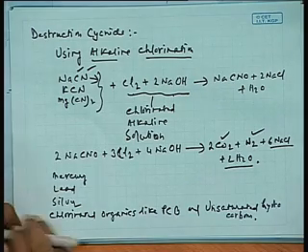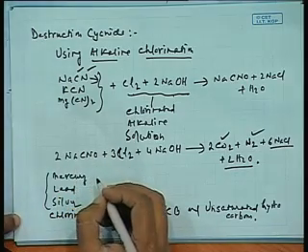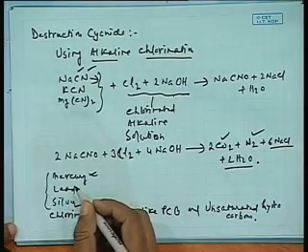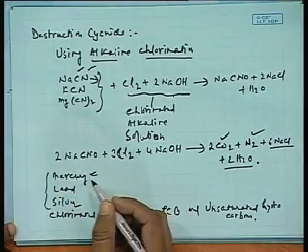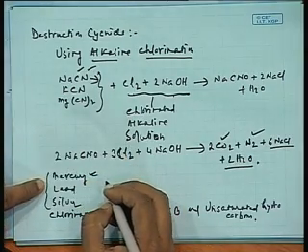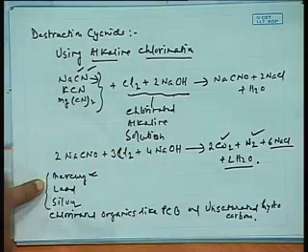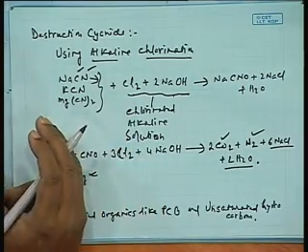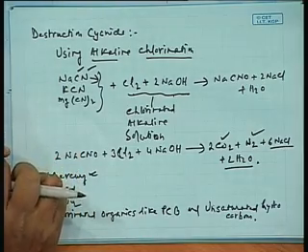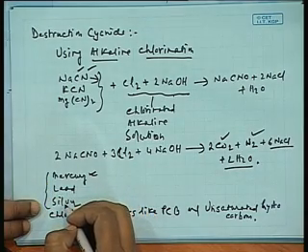You can see that when you are targeting a particular metal, say mercury, in a particular source of industrial water or any other water for drinking water purposes, you have a high dose of mercury. This mercury cannot be simply taken out by, say, a lime precipitation technique. You have to have a technique like redox reactions, where these things can be handled separately.